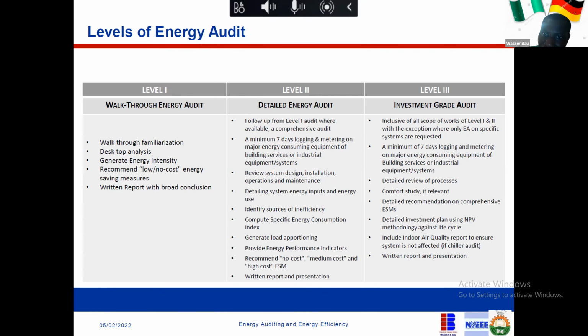But Nigerians are beginning to understand it, and thank God for the advocacy. You see, if you're deploying a solar system in your house, most times I will encourage you to take out the ACs, and some hotels are beginning to learn it. Yes, they will tell you, it's only when there's NEPA, there's AC. When there's generator, that's how they put it, right? Because when you are putting ACs in the whole network, the number of panels you need, the number of batteries you need, might be beyond what you anticipate. So you need to apportion the loads.